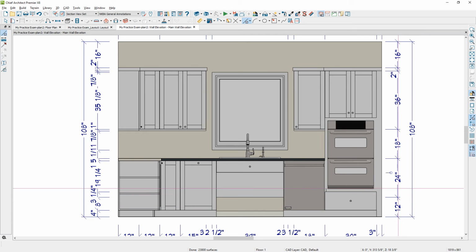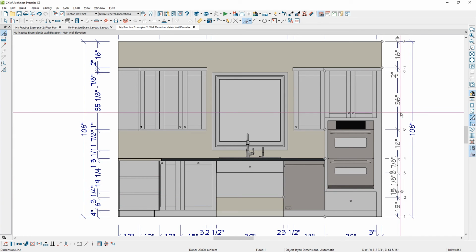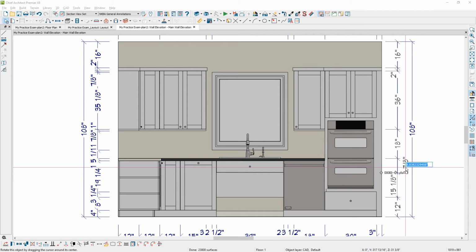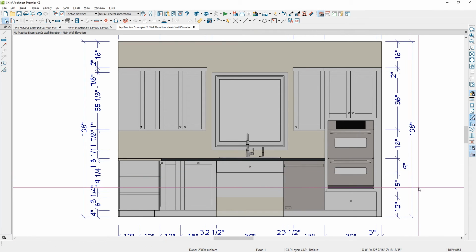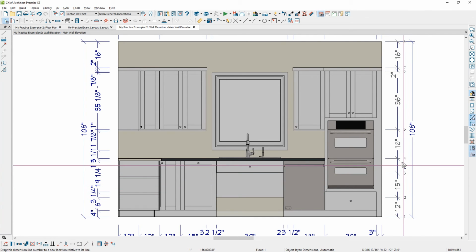Once that line is drawn, I'll click back on the dimension tool, come over here, then pull it up, and you can see that it has it. Once it's highlighted, I'll click on the extension and maybe just pull that through the line. You may need to then pull your dimensions back. Let's go ahead and pull that back a little bit. If I click on the line, you can also set it to be more precise. In that case, I knew that was 9 inches. I now have that breakout that I want for dimensioning to that face item.